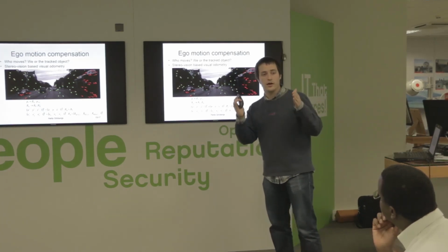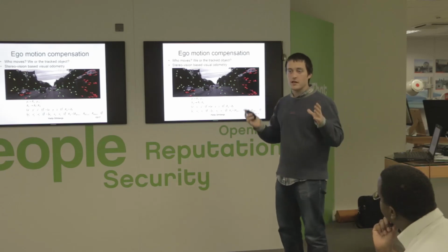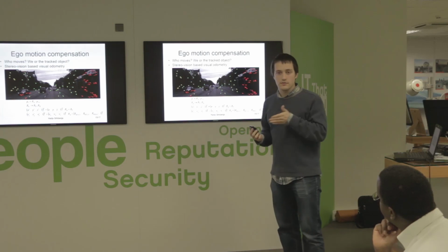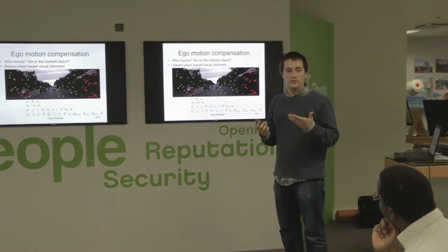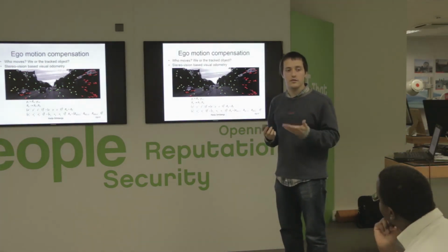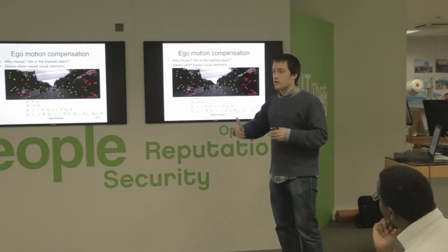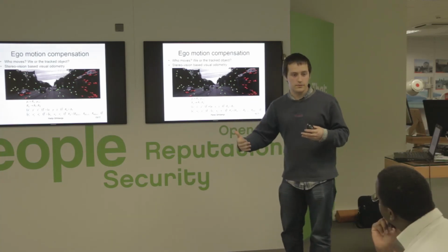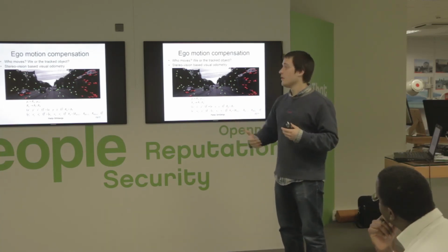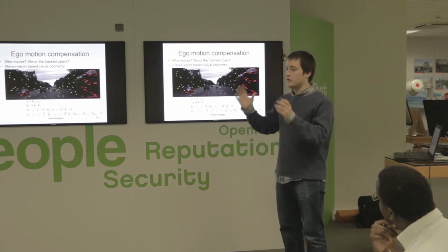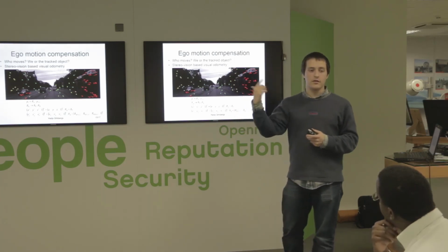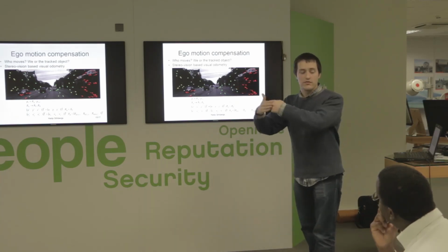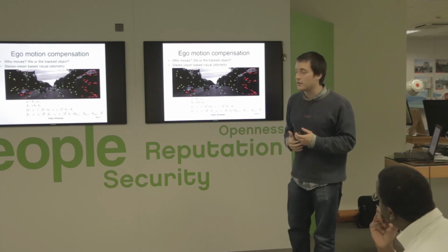So here I use stereo vision based visual odometry, because if I have two cameras, I can actually use the same point cloud to track points in it, and I can calculate my movements also in real life, in units like meters. So I could calculate my own movements, then I filtered it, then I got speed over time, and then I compensated the trackers so I could see that the car is moving, or that I'm crashing into someone, or someone is crashing into me, or something like that.